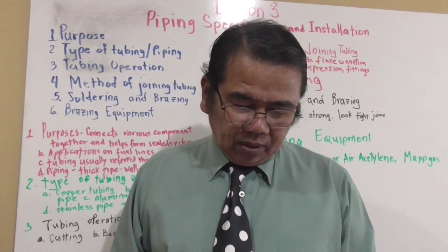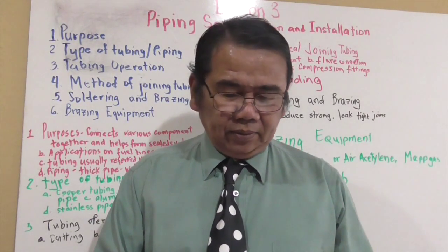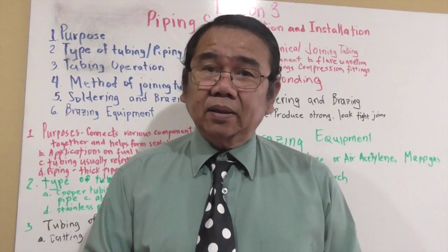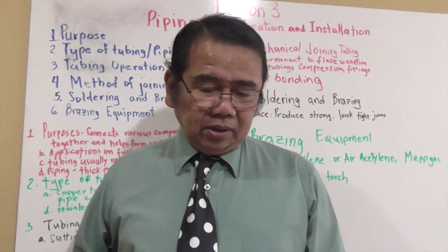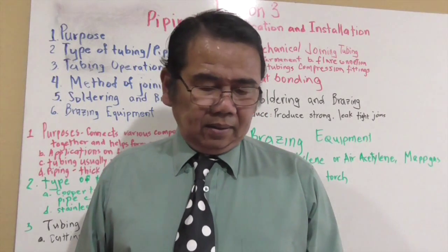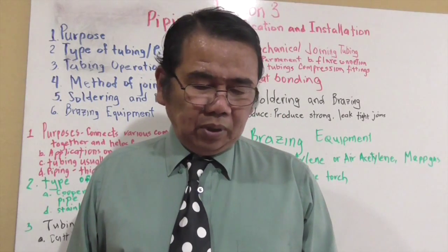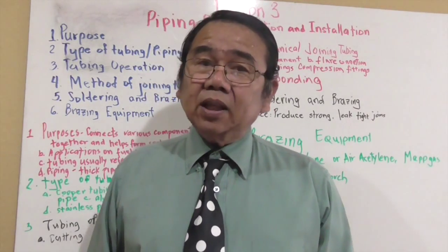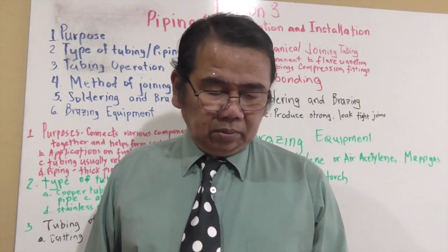Flare nut wrench not recommended for compression fittings. Okay. And now we're going to talk about heat bonding. We do heat bonding by soldering or brazing, using solder that melts at a temperature lower than the metal. When melted, solder flows between the two metals. The difference between soldering and brazing is the temperature at which the molten solder flows.